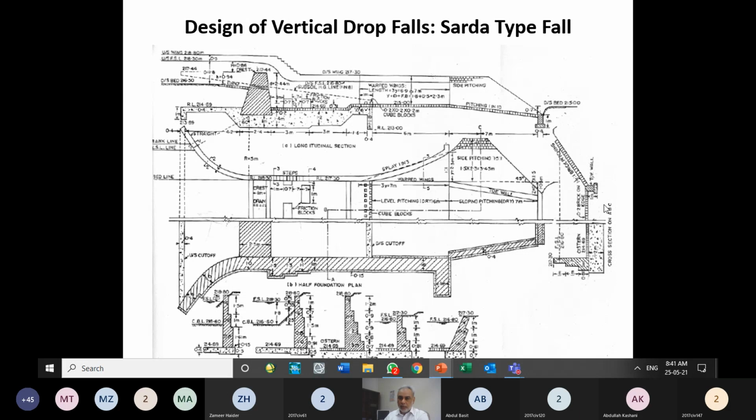A, B, and C. So the left hand side is showing you the cross section over here. So this is showing that there is no trapezoidal cross section. It is a rectangular cross section. Over here, this wing wall is simply a vertical wall, while the section at location C is telling that at this place a trapezoidal shape has been achieved. So you have to either rotate your head to see it, or you have to rotate this page to see it